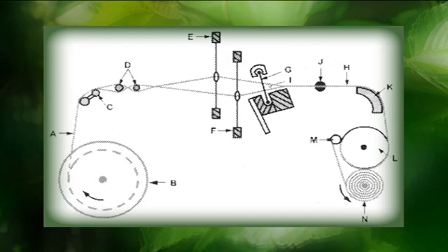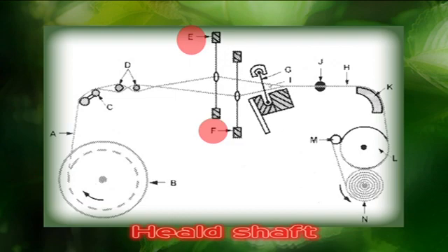Figure 1 shows the passage of a warp sheet and cloth through a plain power loom. A warp sheet A from a weaver's beam B passes around a backrest C and is led around Lees rod D to heald shafts E and F, which are responsible for separating the warp sheet into two layers to form a shed.